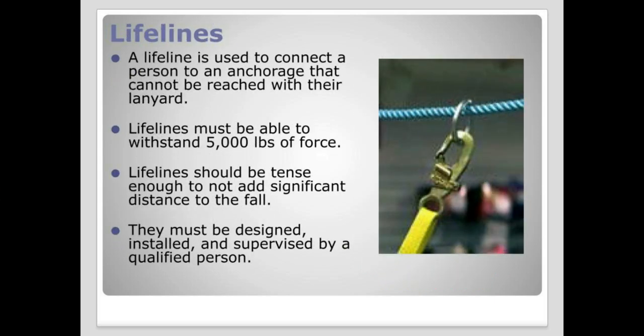Let's talk about lifelines. A lifeline is used to connect a person to an anchorage that cannot be reached with their lanyard. Lifelines must be able to withstand 5,000 pounds of force. Lifelines should be tense enough to not add significant distance to the fall. They must be designed, installed, and supervised by a qualified person.